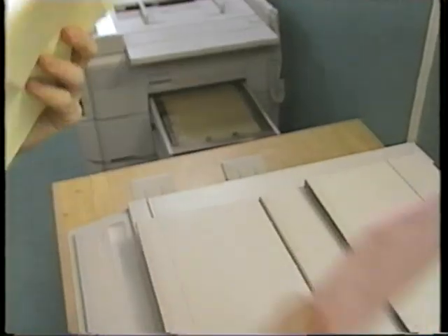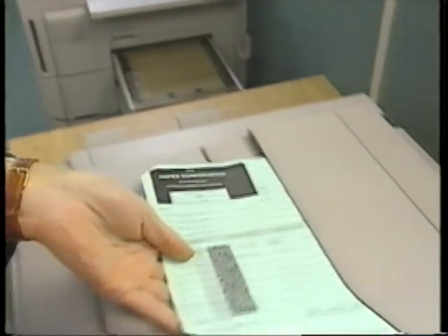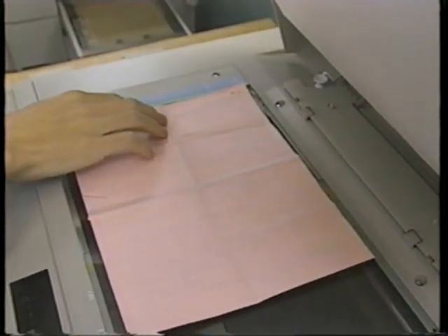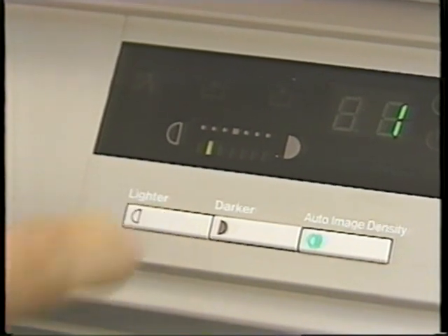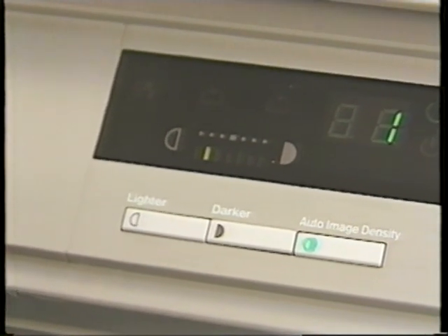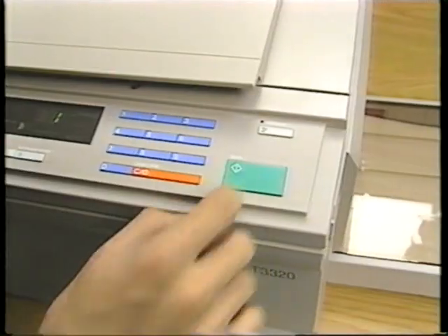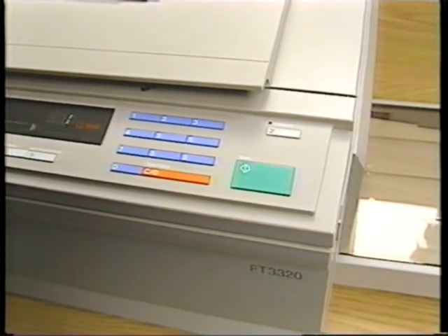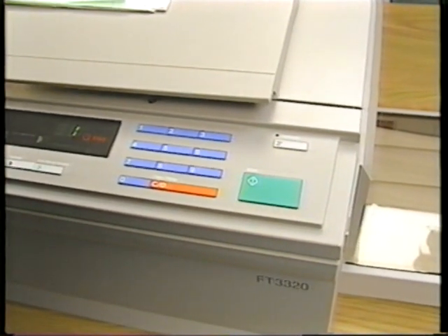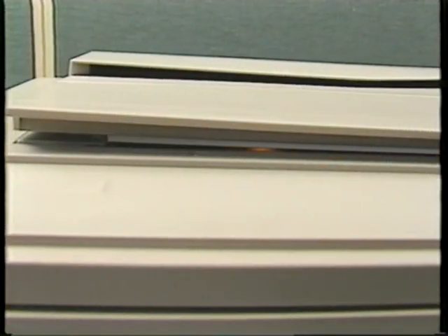Original documents vary quite a bit. Some are much more reflective than others, depending on the type of paper and the information contained. This could cause severe fluctuations in copy quality. To compensate for the variation in originals, copiers use some type of image density control, manual, automatic, or both, to adjust the brightness of the exposure lamp. Some automatic systems work like this.